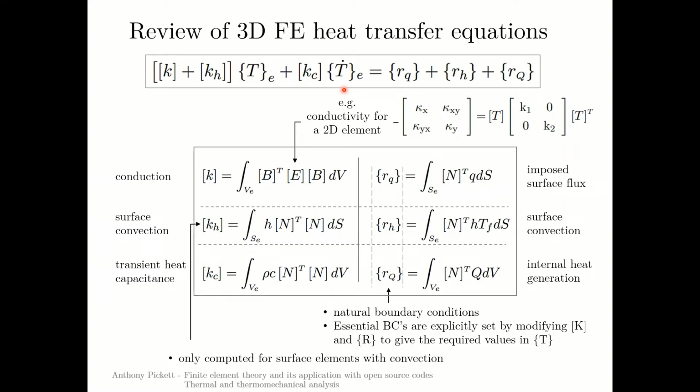Just to make one point clear, there are only values in here for the certain nodes where these particular heating elements occur. However, this total vector will be the same size as the total temperature vector for the structure. It will contain very many zeros.